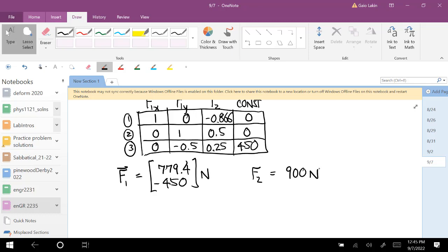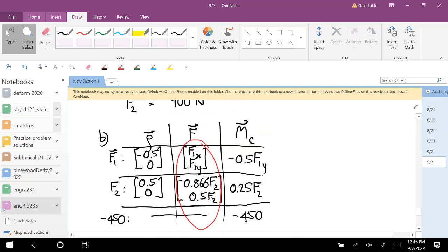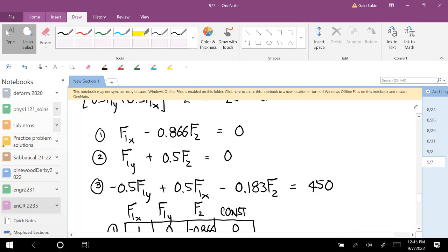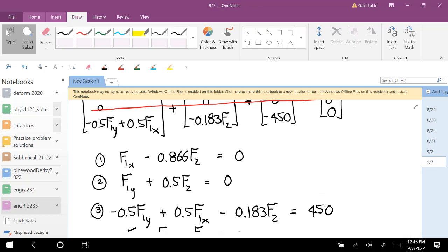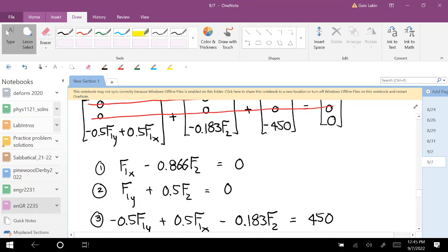So now this is really close to 2D rigid body statics, and to do 3D rigid body statics, it's really not any harder. You have to know the third component of your row vectors, the third component of your forces, and then when you take a cross product, you have 3 components of the moment, so you have more equations to plug into row echelon form, but conceptually it's exactly the same.